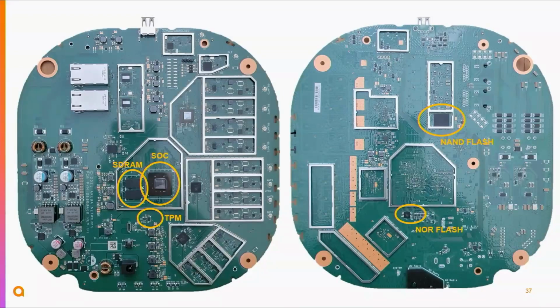So these are what those components are. On the board, this is that SoC, that Hawkeye SoC that has the CPU and lots of other components. SDRAM, 2 components here. The TPM part, I finally found it. Please don't tell me, Farhan, that it's the wrong location, okay? Flash is here, and then NAND flash here, NOR flash here.